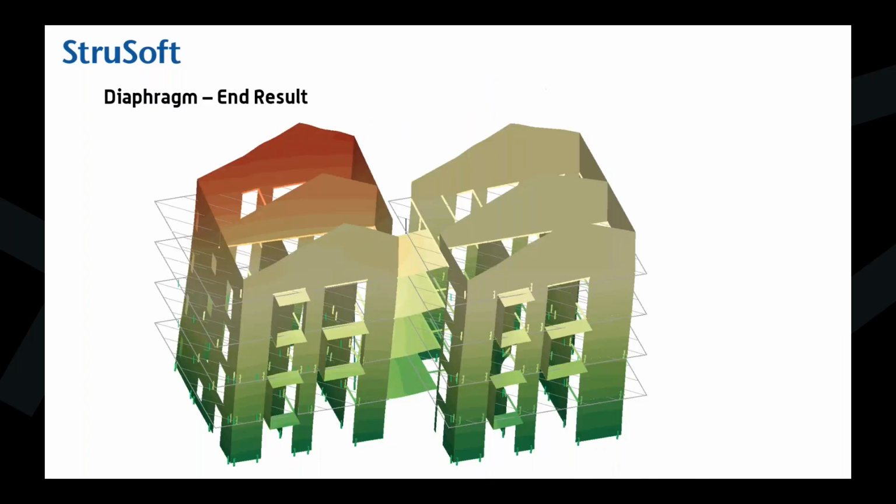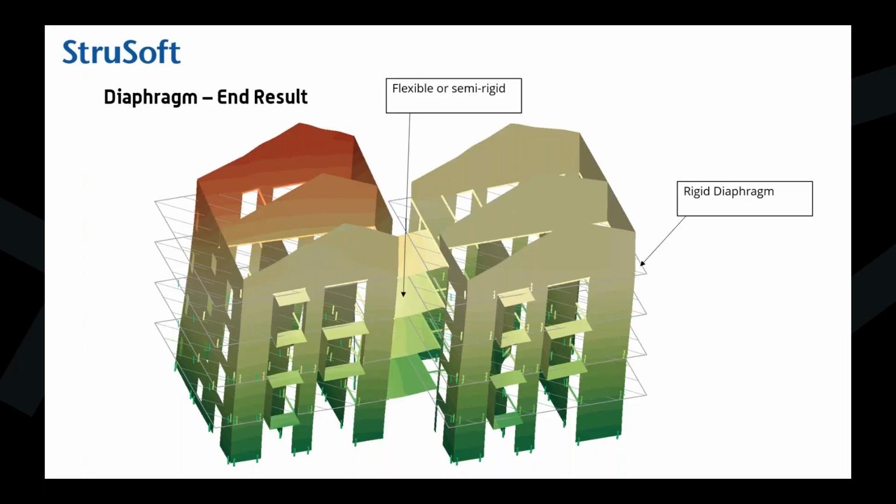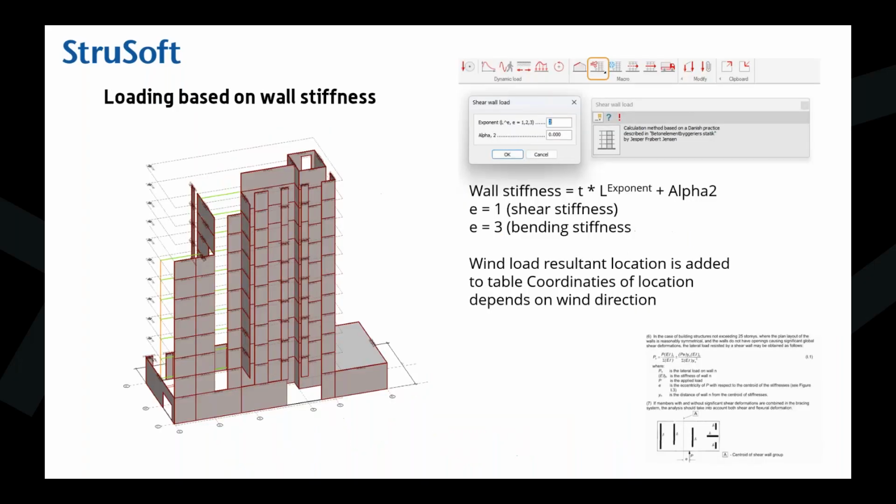You can also use it if you have some regions, like we have a square building, so probably there's no shear deformation going on in this part of the building. And same here, but in between we might have some semi-rigid regions. So we can exclude or include certain areas in the rigid diaphragm. We can use semi-rigid theory in between those buildings to save those finite elements for the important use, not to use them for the walls. So there's flexibility in the middle. You can even use no rigidity at all in this area if it's really only a few hollow cores, or you don't want to take the growth or the edge pass into account.